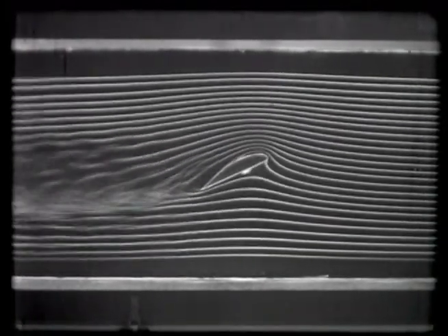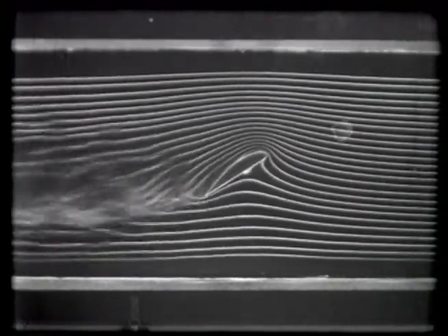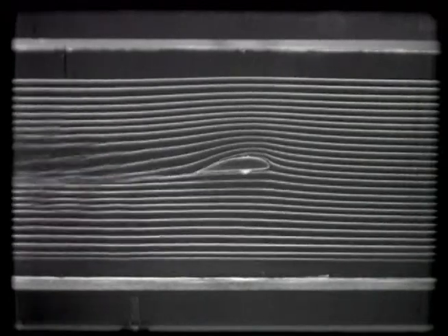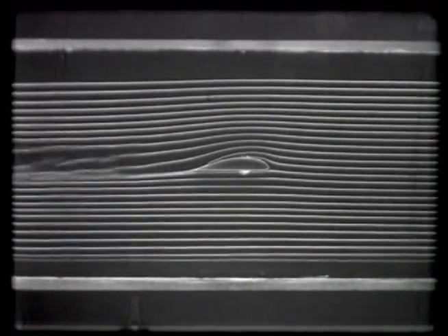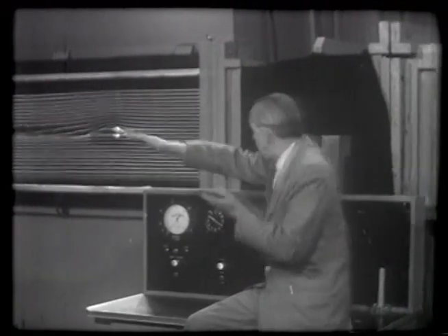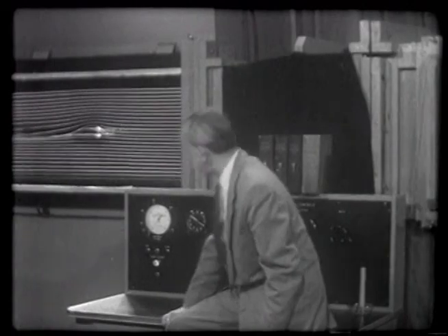You see, now I can go quite a bit up with this wing until it stalls. And when I do this boundary layer suction very slowly in the normal range where we want to fly with high speed, then I even reduce the drag with it, because the dead air, which has lost its momentum, will now be sucked in and accelerated through the blower system.